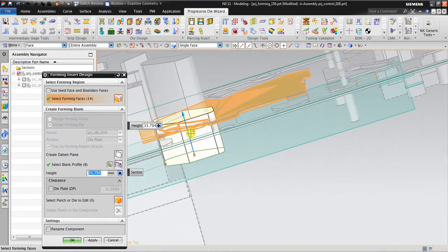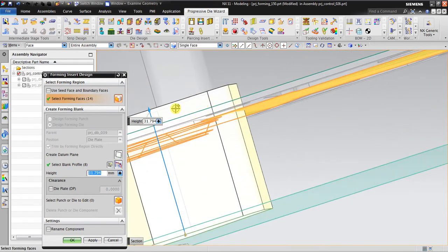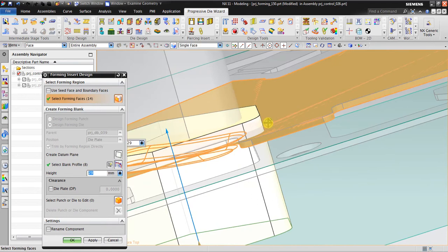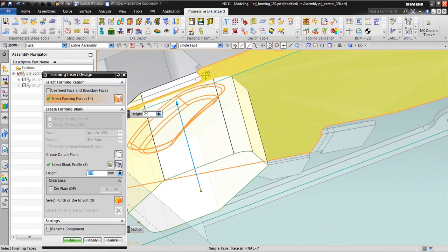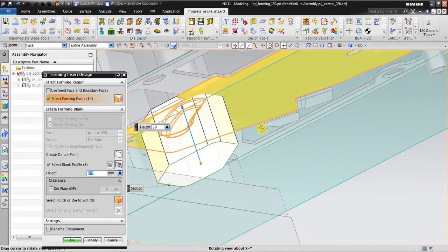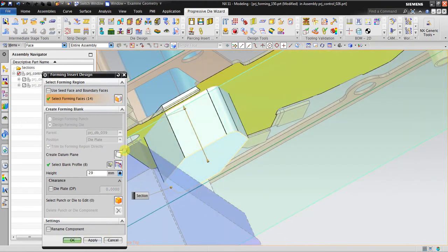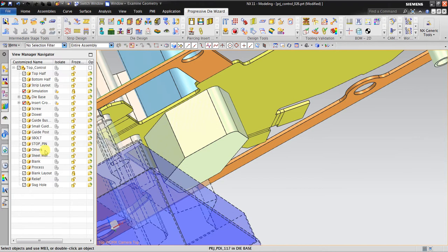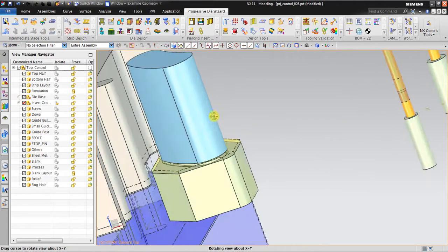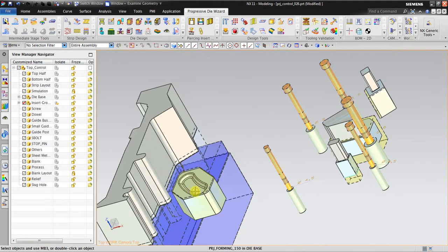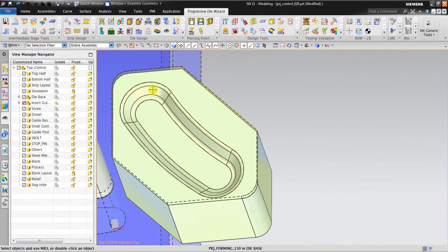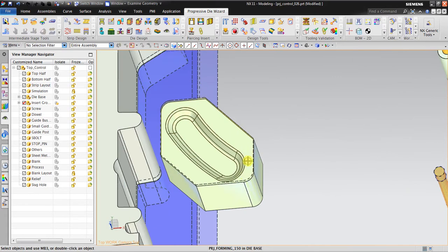You see, it will extrude slightly over the part, but we see here there's a boundary surface, so it means that trim by forming region directly will trim based on the surface in the sketch, and also based on the surface. When I click OK, you can see the result. If I hide the simulation, and also this one, you can see it creates a good die here, a smooth shape taken from the lower side of the part.